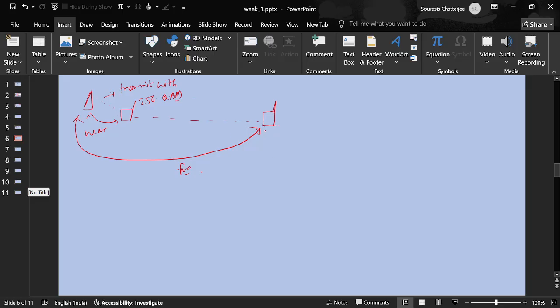So one of you mentioned Doppler. Doppler is really a complex thing. We are not encountering it here, at least in this context. We are just purely drilling based on SNR. So the issue, as you correctly told, is that when the user was very close to the base station, it asked it to transmit with 256 QAM. Now suddenly it moved very far.